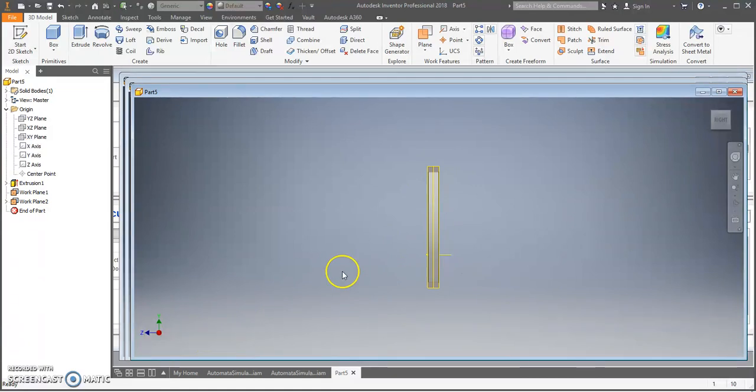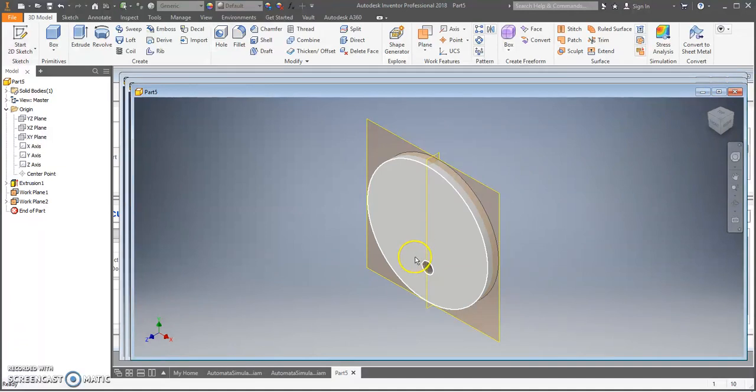Hopefully you can complete this on all your cams. It's the same process on all your other cams. With the snare cam, you don't have a line of symmetry. You just line it up with the edge of that snare. If you have any troubles, hopefully you can get that figured out, and hopefully that helps you prepare your automata.